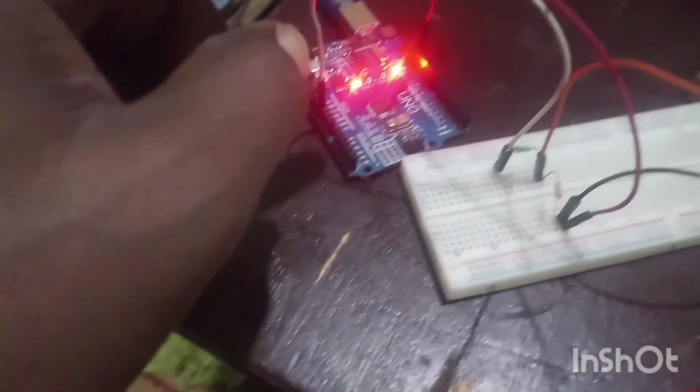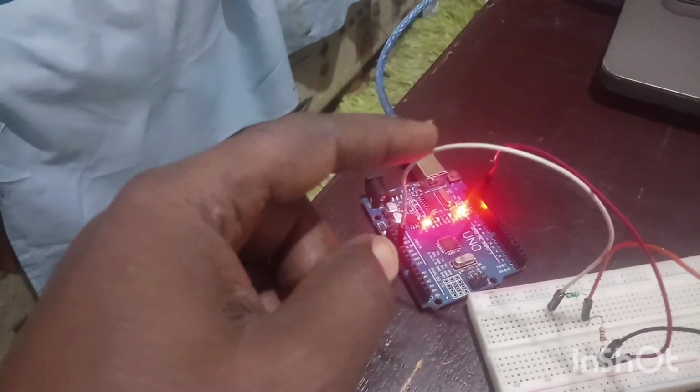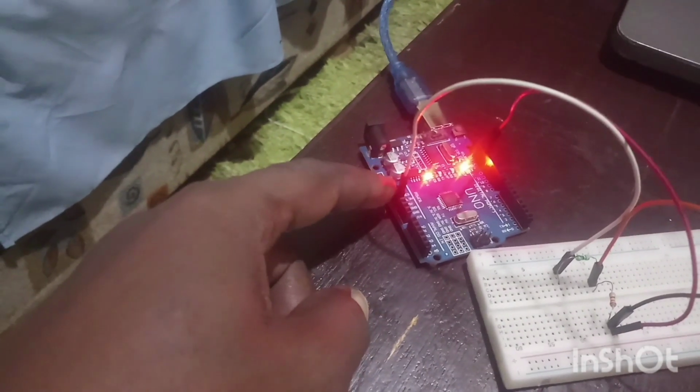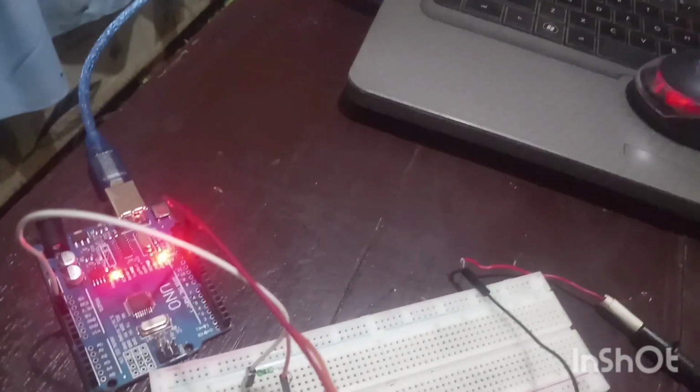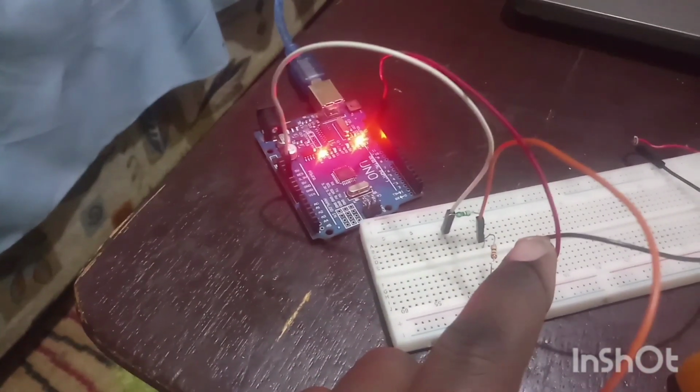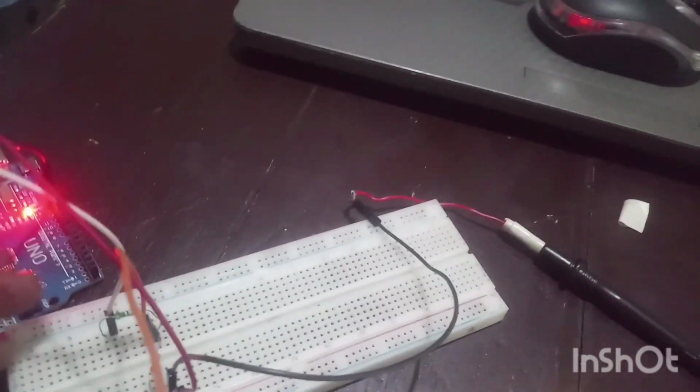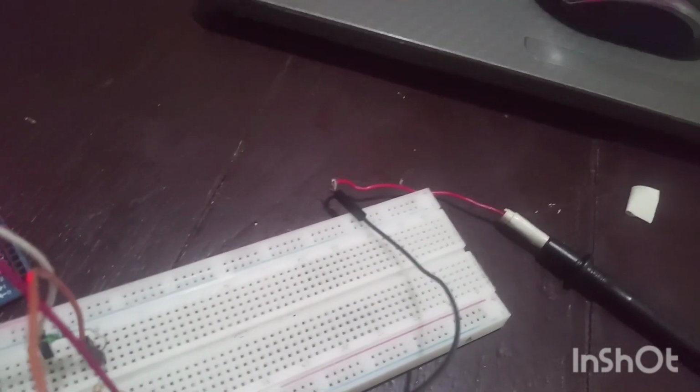Now this white wire which you are seeing, my hand is touching, is going to the 5 volts of the Arduino here. And then the red wire, which is this one, is going to the ground in the Arduino, where my finger is pointing. I've connected the top of R2. So when I'm taking the entire 5 volts, all I need to do will be, I'll have to take this.